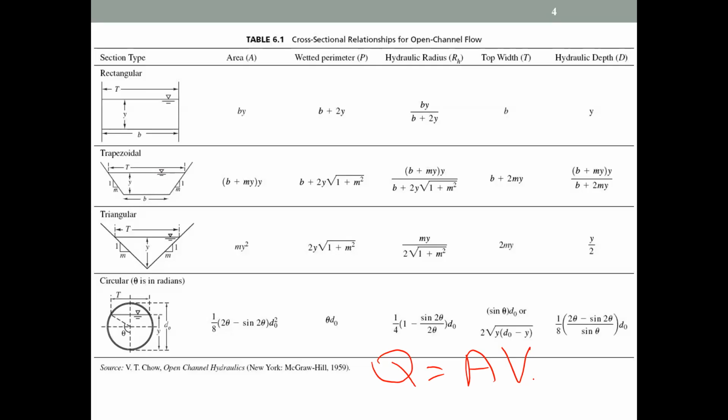And there is one condition here. The cross-section area that you consider should be perpendicular to the average velocity. That is the condition. Now you understand that whenever we are going to find out this flow rate, it doesn't matter whether we are talking about the pipe flow or the open channel flow, we always have to have the idea about the cross-section area, right?